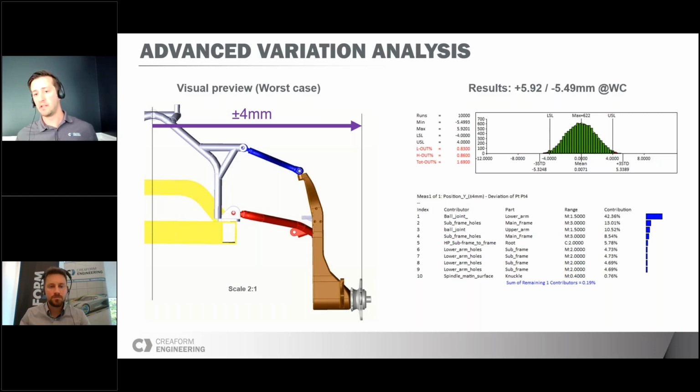So if your CP is good and your CPK is bad, then this is not a variation issue. This is a bias or a shift issue. So you really need to look at both together. And isn't there another indicator, CPM, that includes both, which is more related to the machine side? Yes, CPM is close to CPK. The calculation is a little bit different, but it's a similar indicator to CPK, if I can say it like this.